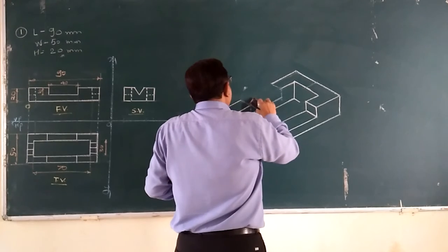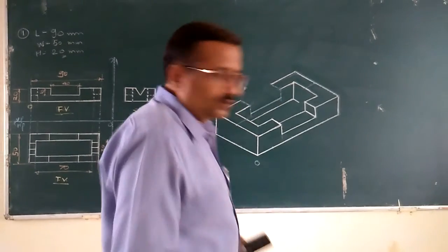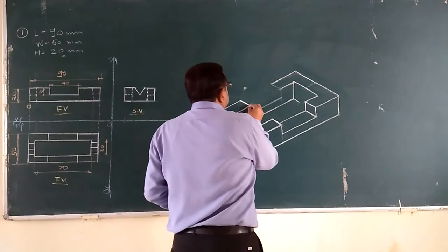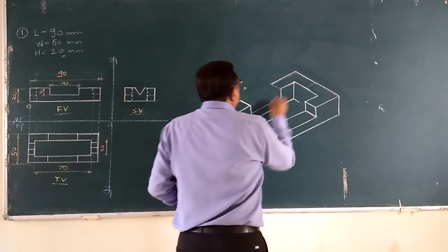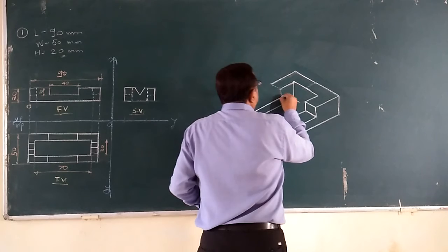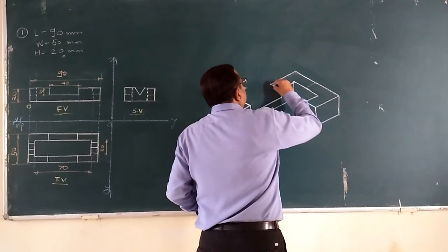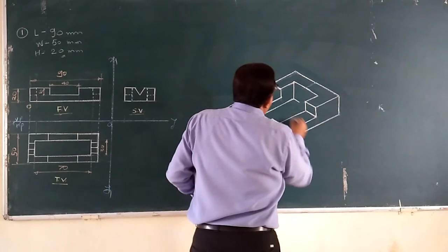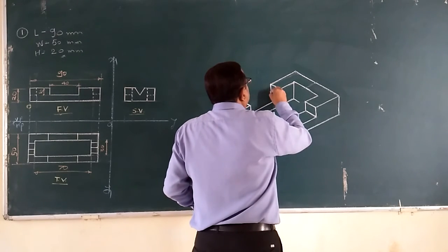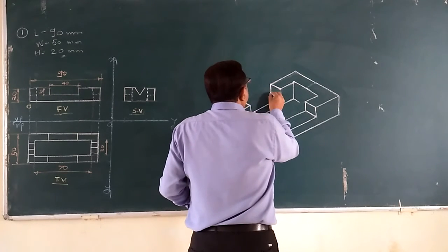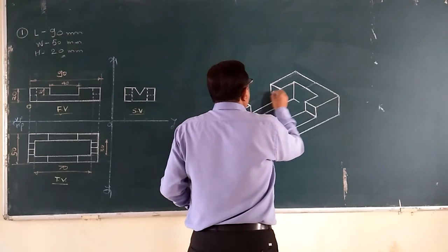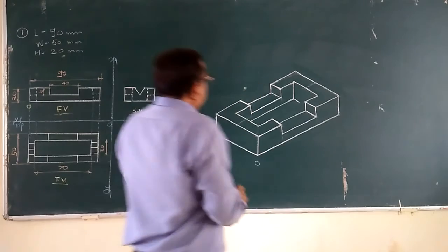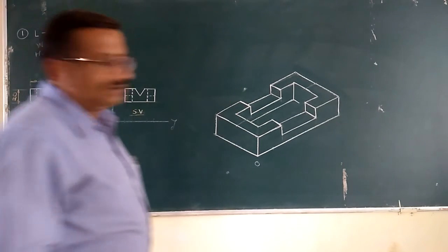This much part, after sawing, as a scrap we are just throwing it out. So naturally, this much will be retained with us, and that much part only we should show by dark line, bold line, or continuous thick line. That will be 10. Again, this corner again parallel to right 30 line you have to draw straight, so that in that one also we have shown that cutting.